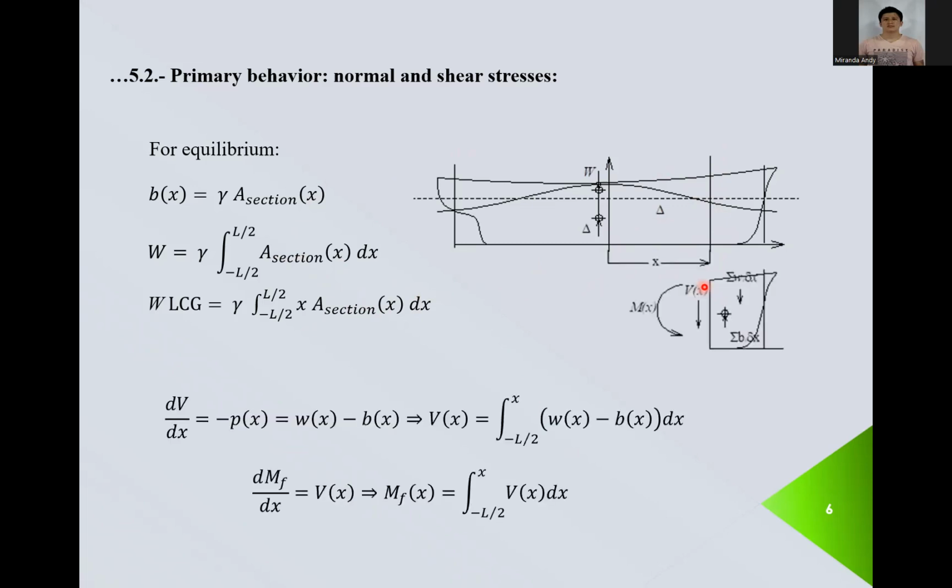This is the figure that I'm showing here. If I take this cut from here to here, this is an equilibrium. But in this case, we have to consider both. Remember, this is a negative phase. So this is shear force, downwards, positive. This is bending moment. In this direction is positive according to the Classification Society convention. Remember, it's opposite to the one that we use.